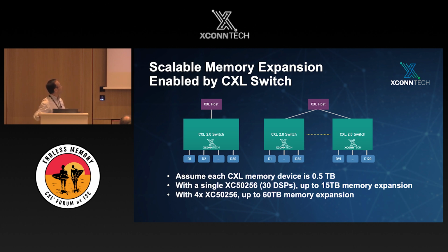All these hosts support CXL 1.1, and the memory devices are single logical devices, SLD, as of today. However, in the future, or next year, we do see these hosts going to 2.0, and the memory devices going to support multiple logical devices, MLD. And our switch works in both cases.